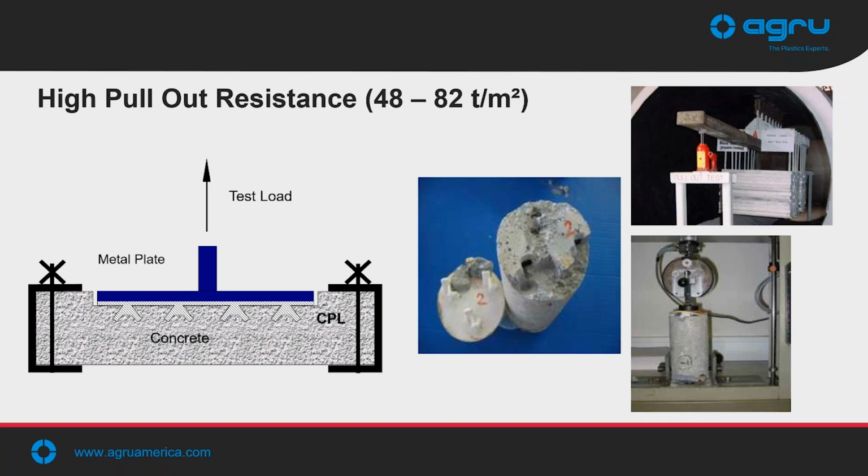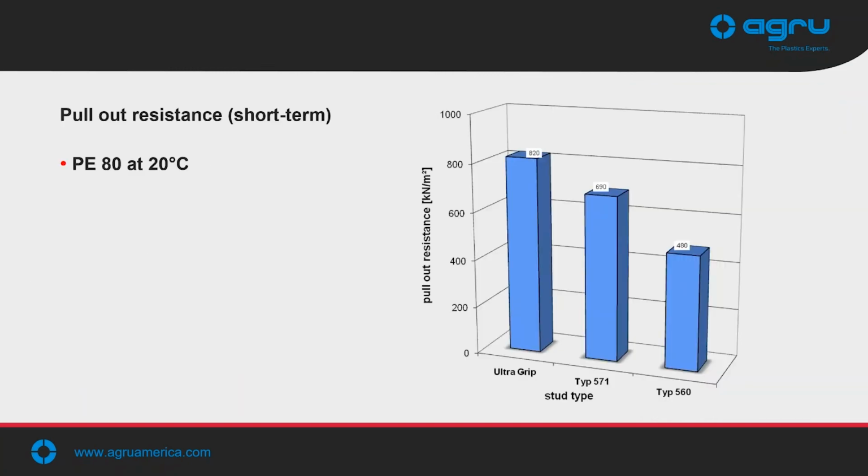In this case, we've got the concrete protective liner. We've cast that into a slab of concrete. We attach a force to that concrete protective liner, and we increase that force until the concrete protective liner pulls out of the concrete. So if we were to hang something from a liner, this would be an applicable test. If we were to have a vacuum that was created, this is somewhat of an applicable test. But more often than not, what we're concerned about is back pressure.